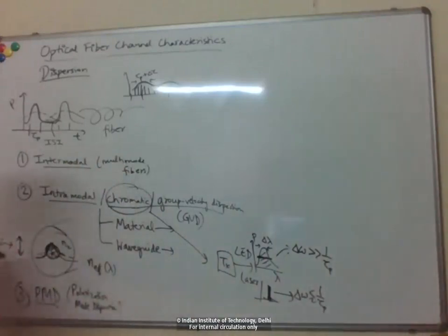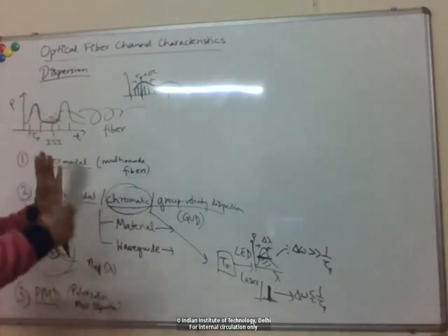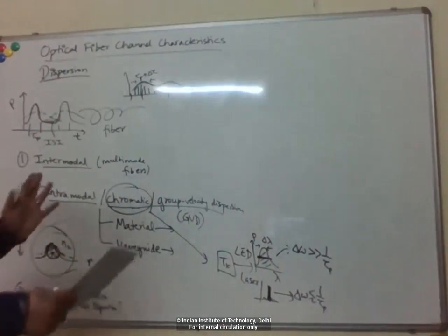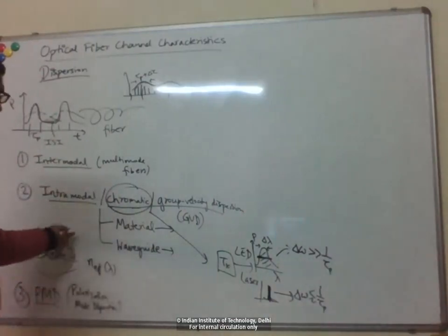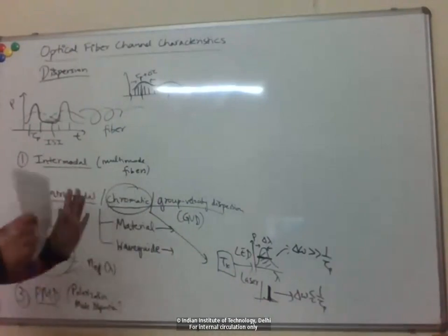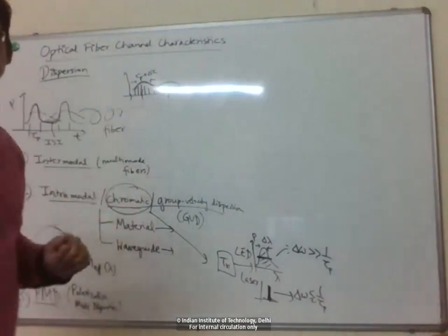And that breaks the symmetry between these two polarizations. So in certain sections of the fiber, one of these travels faster than the other, right? So your input signal, which is composed in general of both these polarizations, because of these fluctuations in the speed of the two orthogonal polarizations, also leads to some broadening.